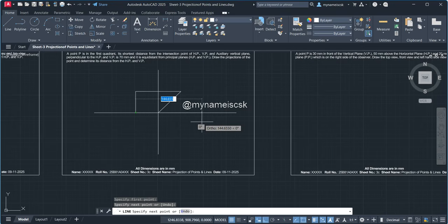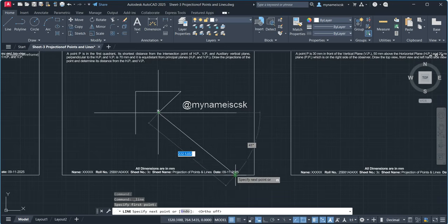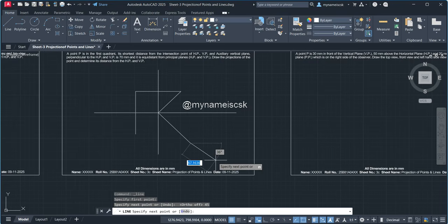Okay. And again same, select this line, use the mirror command and give the point no. So automatically you'll get it. If you want to draw this point with respect to the side view, then you have to take a line of 45 degrees, any random length, 100 tab 45, and then you have to make the projections.